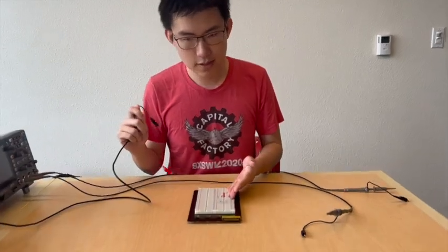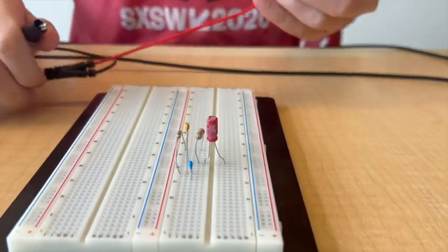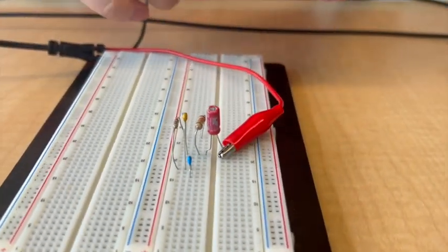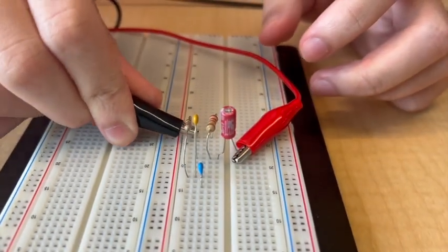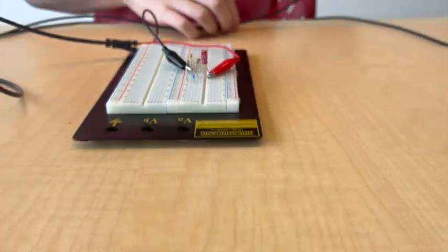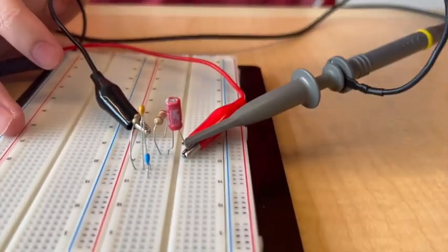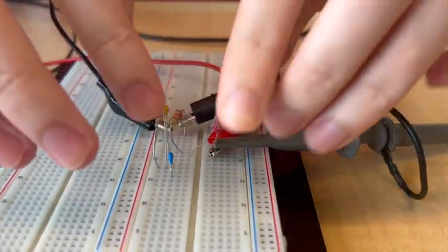Right here in front of me is our circuit already built, and we are going to hook up our signal generator leads. For this one, we want to hook it up to the 0.1 micro, and we're going to hook this one up to our ground. In this case, my ground is right here. This is a little bit of a different setup than the one you're used to. We are going to use our oscilloscope without a bus to measure our input signal. So I'm going to use my oscilloscope to measure the exact same thing. You won't have to do this, you will only have just the input signal, and that will be that.